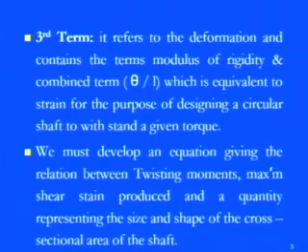So the meaning is pretty simple: as you move along L, right from the origin to the extreme, you will find that theta is also increasing. Since the distortion is more, you can simply capture this kind of distortion or deformation in terms of strain, and this strain is known as the shear strain.